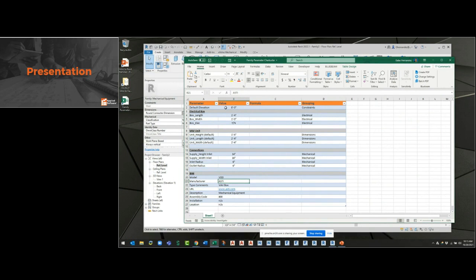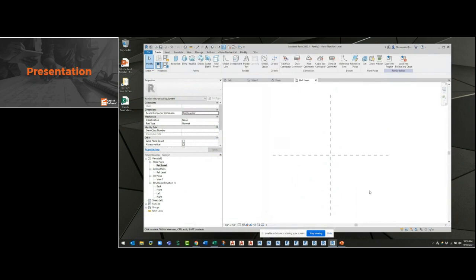So the plan is, with the default elevation here, I'm going to need to create some electrical box parameters, the actual VAV parameters themselves, connector parameters, and then fill out some of my BIM data, right? So we'll get to that in a second. So this is the plan right here, okay? Now, what the actual family is going to look like, you just pick a spec or choose whichever one the manufacturer provides, or what have you.